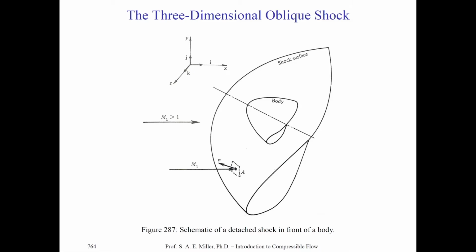So we might know from this a particular incoming Mach number and relative angle, even though it's not exact, based on the normal direction between the vector Mach number coming in and the normal vector. And so we know from this, perhaps we can analyze the wave angle and incoming Mach number and find the properties locally at each particular differential element across the shock itself.